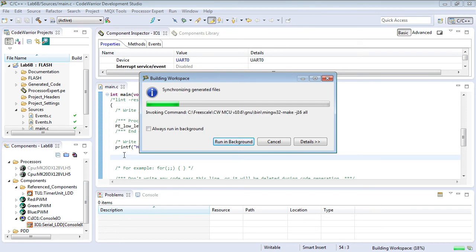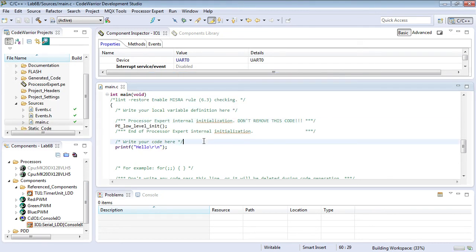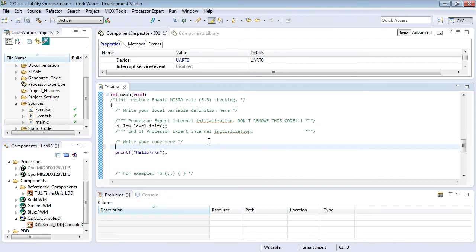Now, of course, in printf, one thing that you can do is convert integers. So let me give you an example. Let's say I have a uint8 value, which is called red, and I'll initialize that one to 0. Then I can print out that value by using the %i for integer conversion and put that here in my printf command, and that will print out the value that you see written there.